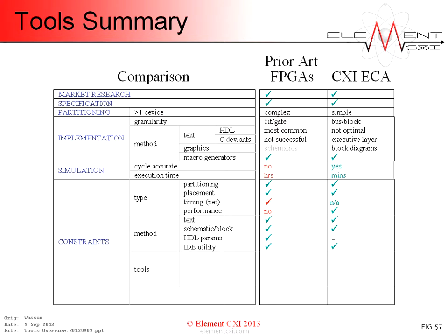Specialty tools for constraint application include pin and I/O bank planners, and chip and floor planners, all employed by current FPGA tools. Pin planning isn't applicable for the bus granular ECA, but I/O bank planning is, as is floor planning, but at a higher operator and region level. Presently, FPGA tools are too overwhelmed with bit-level minutiae to implement a bandwidth manager, a tool to constrain implementation by high-level parameters such as samples per second.